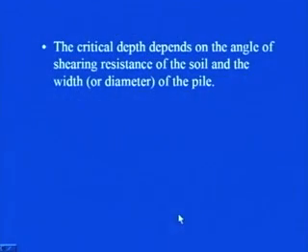Now, this critical depth depends on the angle of shearing resistance of the soil and the width or diameter of the pile. Depending on the width or diameter of the pile and the shear strength parameter of the surrounding soil, this value of critical depth will change from one pile to another.